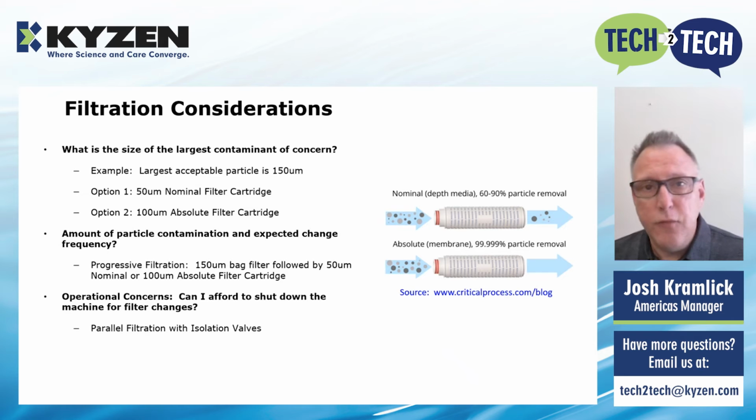Operational concerns. Can I afford to shut down the machine for filter changes? If the answer is no, then parallel filtration with isolation valves is necessary.